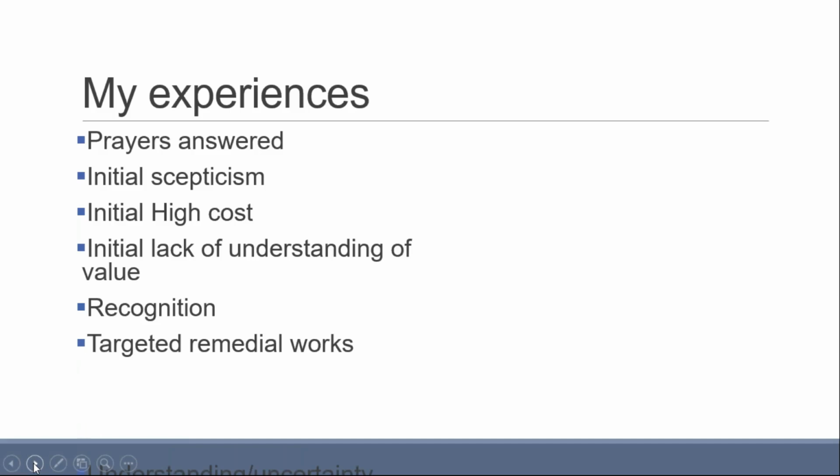And of course, one of the big benefits of being able to say precisely where a leak is, both in plan and elevation, is that you can do targeted remedial works. And I can almost guarantee that you will save 10 times over the cost of any survey when you're able to focus and target remedial works, rather than guessing and overestimating either in longitudinal extent or in depth.